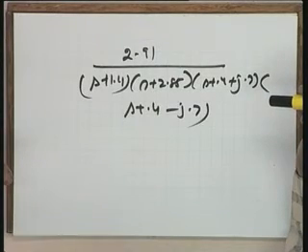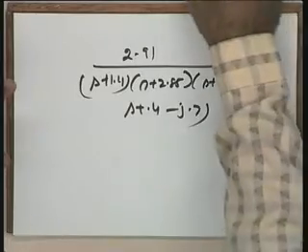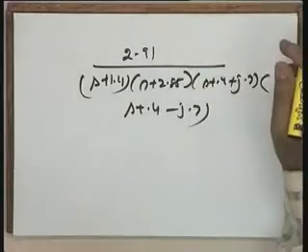So graphically, can we get 2.95 accurately? Not, this is what I said, that probably you cannot. Yes, you can, provided you have that much patience, and it is difficult to have that much patience, and therefore it is a rough calculation. After all, you want to check the dominance condition. Even the dominance condition is not quantitatively known, so it is a rough estimate of where the pole lies.